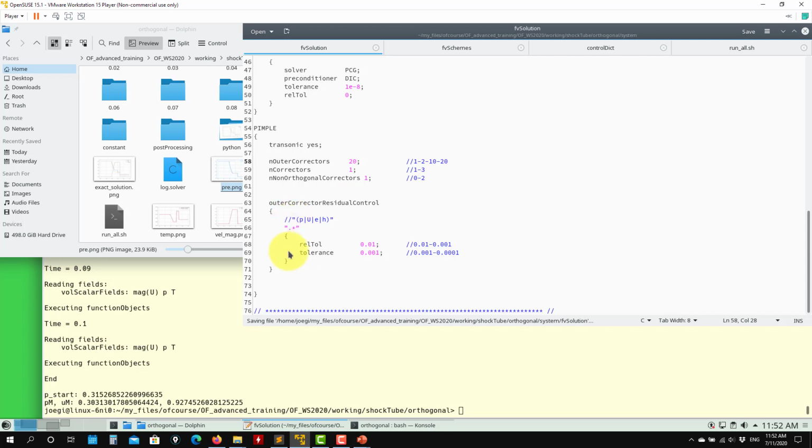Then I put this one. But be careful that when you add this one, sometimes it will take many iterations, so you need to monitor the residuals. But in general, doing 2 iterations is good, to alter the corrections. Most of the time I do 5, and I pay attention not to do more than 10, because more than 10 starts to become very expensive.